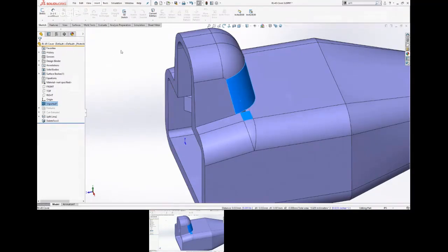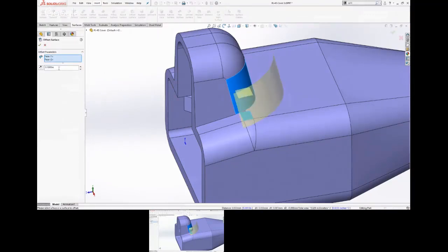So unfortunately in SolidWorks, there's no visible copy surface feature. If you search for it, it doesn't exist, all right? But I'm going to show you where it's at. So on my surfaces toolbar, I'm going to do an offset, a surface offset. So offset surface, okay? And you can see it defaults to 100. That's just what it defaults to. Right here it says offset surface, right? Watch when I type in 0 and hit enter. It changes to copy surface, okay?